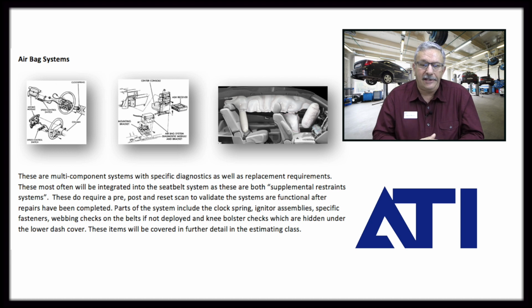If you have somebody that's of significant weight that hits the airbag system, there's also a collapse capsule that is in the steering column that, by manufacturer, they give very specific measurements for. It's wise to go in and just check the distance and make sure that the distance in that crush cap is where it's supposed to be, because if not, then the steering column itself has to be replaced. So these are pretty important things in that whole integrated airbag system.